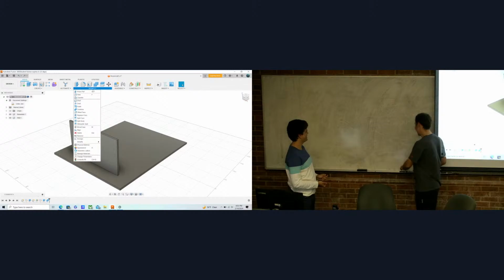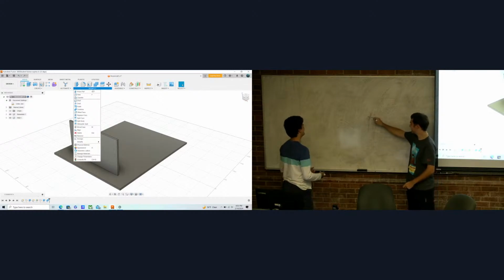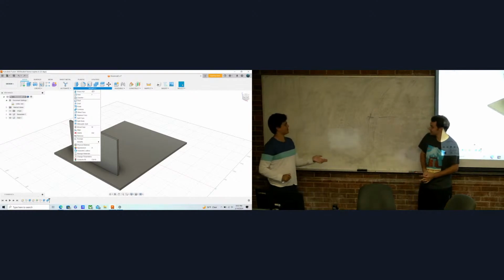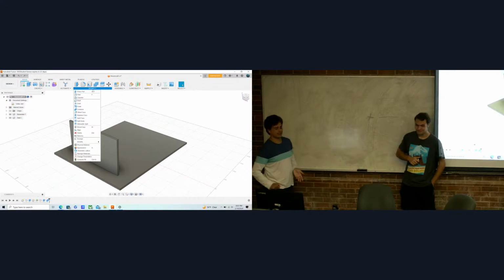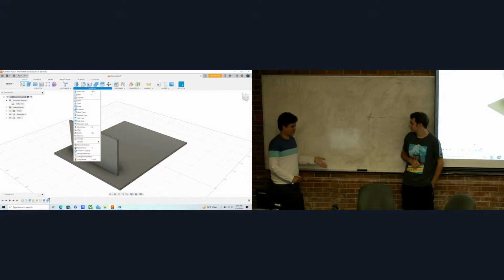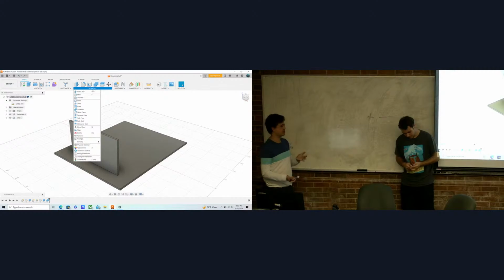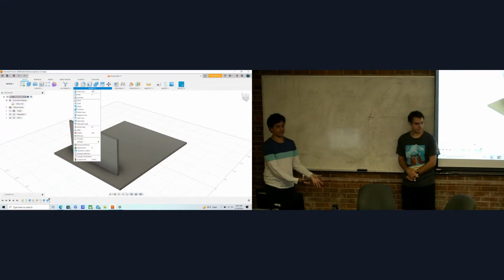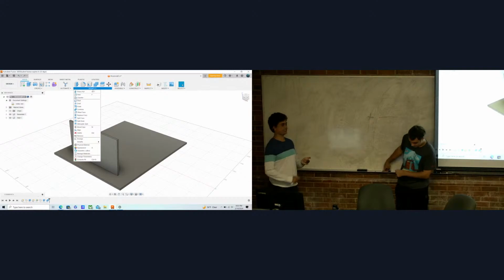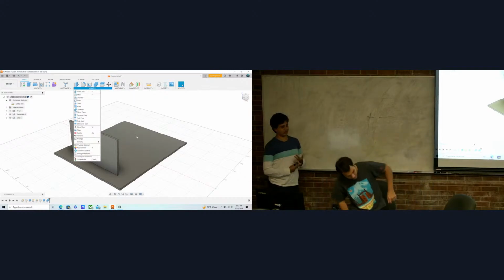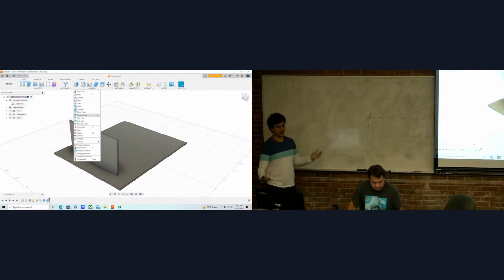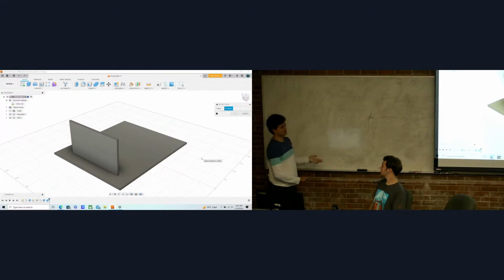What is that? Additive and subtractive. Oh, okay. So there's different types of manufacturing methods. The main two are additive forms of manufacturing and subtractive forms of manufacturing. The most common form of additive manufacturing is 3D printing. It means you're adding material to the piece of work to make a bigger thing. And subtractive manufacturing is honestly mostly everything else: CNC milling, using a lathe, using a laser cutter, as we're doing. All of those take a larger piece of work and then cut away at it to manufacture the final piece.